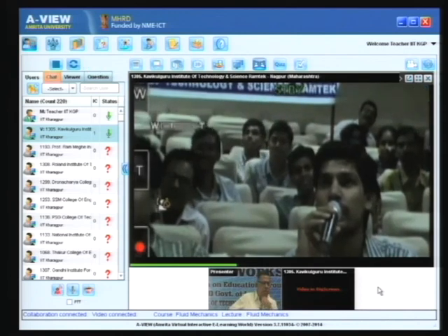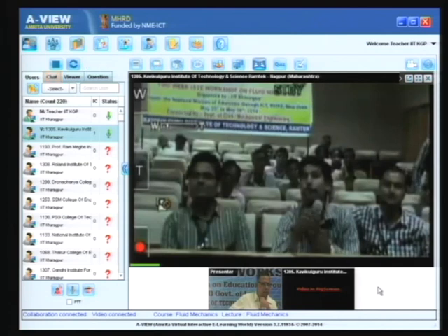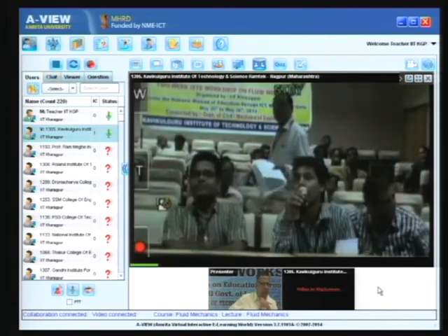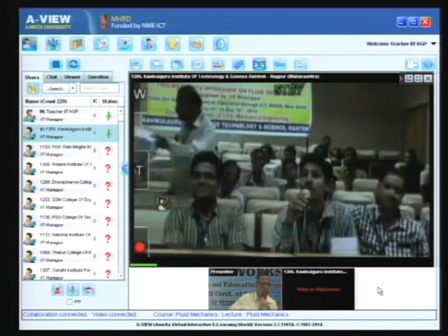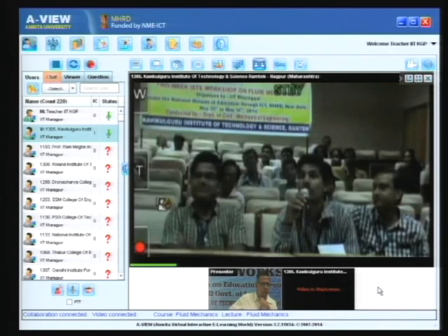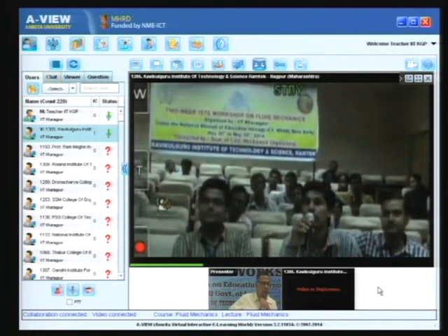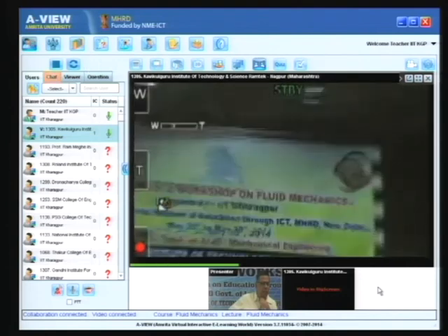Suppose the fluid is at rest and the container is at rest, and then you suddenly start to spin it. There will be what we call a spin up from rest. There will be secondary flows, a flow in the RZ plane also. Some vortices will be there and then they will decay, and eventually an equilibrium state will be reached where there is only one component of velocity, which is a swirl component V theta. In the transient period you may have VR and VZ components also.